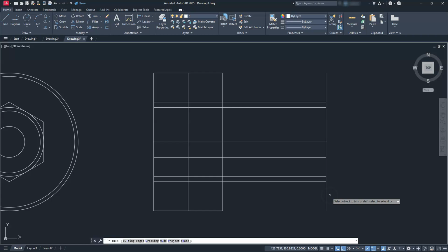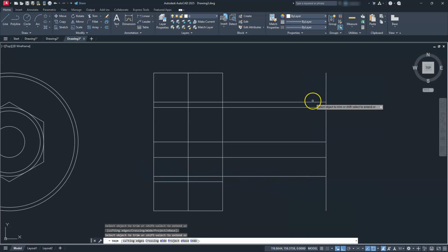Right, so we have a trim command going here. This is the outside edge. I'm going to get rid of that one as well, and this one. It looks like I did get rid of something I did need here in the middle. Yeah, I did. So there's an extra line that goes right across here. Let's go ahead and place that here in a second. But I'm just going to trim off right across here and here. And what I'm looking for is a circle that has a diameter of 9 here in the middle. So let's go ahead and escape.